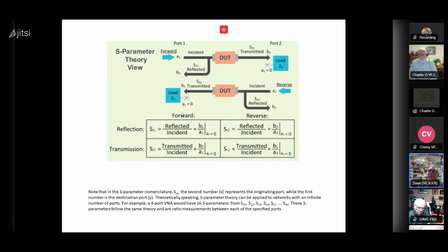Is that something you could do, or is that something you shouldn't be doing with the VNA unless it's got an S22 port? If it's a passive device, let's say a filter, you can do that. It will be effectively symmetrical. You can flip it around and measure the other way around. If it's an active device, generally speaking, you can't do a measurement backwards through it anyway.